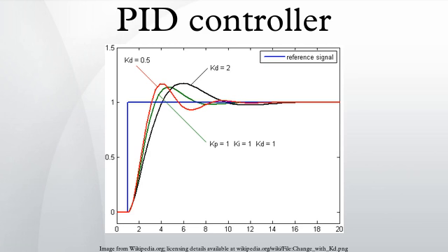This problem can be addressed by increasing the set point in a suitable ramp, disabling the integration until the PV has entered the controllable region, preventing the integral term from accumulating above or below predetermined bounds, back-calculating the integral term to constrain the regulator output within feasible bounds.